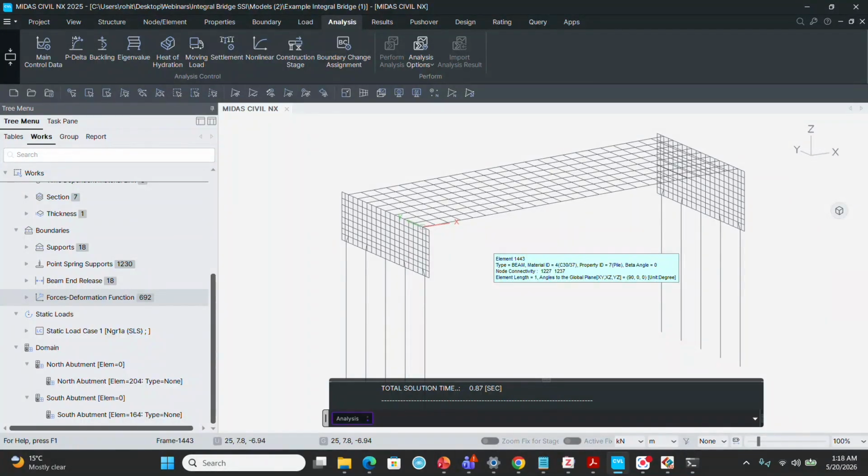So depending upon the convergence criteria that you define, the convergence criteria can be with respect to a certain force like a bending moment or a shear force, or it can be with respect to the settlement or the lateral deformation that you're observing at a certain point. So depending upon the convergence criteria, we can define the number of iterations for a particular analysis, and the iteration with respect to the calculation of the nodal results, the export of the nodal results, and export of the reactions into GTS, and running the analysis in GTS and taking back the updated spring stiffness values into civil. So the iterative procedure has to be done till the convergence criteria has been met.